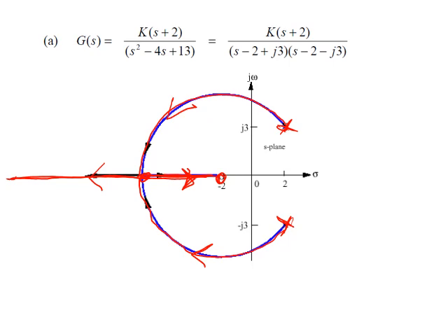Or maybe somebody will get confused. How am I going to draw this? I'm still not clear about doing this one. If you cannot draw it now, wait until you calculate the quantities. Calculate the j omega crossing. If you find that there is a j omega crossing at this point, that means you are going to go this way. And you will continue with the locus. Also here there is a j omega crossing. You will go this way and you will continue. Continue until where? Until the break-in.